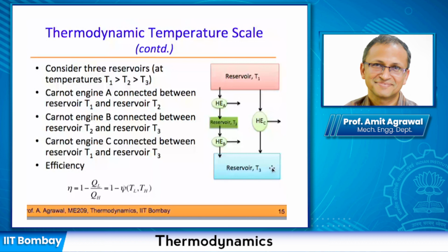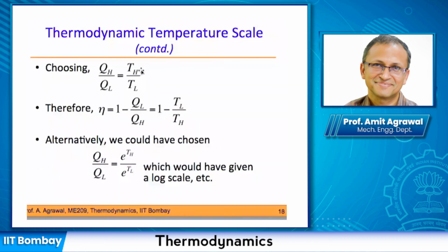But the engine that you can operate will have a certain efficiency. You cannot convert more than a certain amount of work for a certain amount of heat taken in from the reservoir. That is a physical constraint. What temperature values you want to call it is up to you. So what will change if, instead of taking a function like this, you take a square or an exponential? What would change is the absolute numbers, but of course this efficiency cannot change. Does that answer your question?